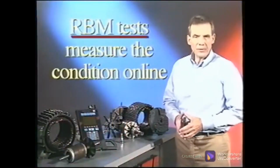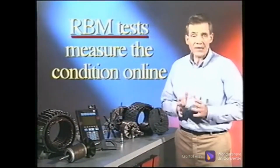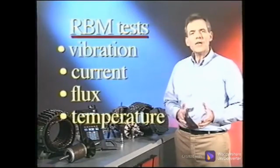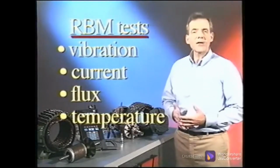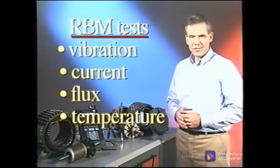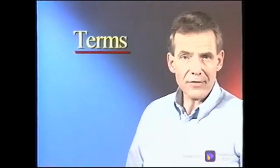RBM tests and measurements can be made to determine the electrical conditions of the motor without taking the motor offline. These include vibration measurements, electric current measurements, flux measurements, and temperature measurements. There are some terms you must know in diagnosing electrical conditions.